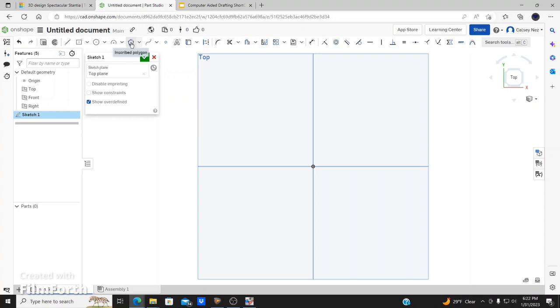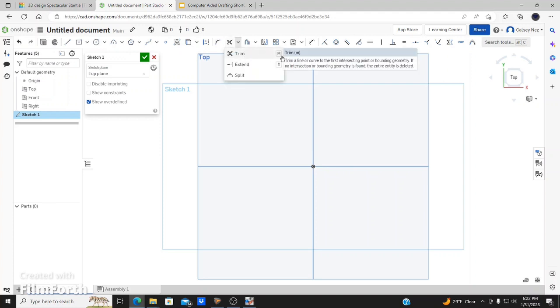Polygons, nothing else. I'll click this right here, nothing. Spline, point, nothing. Text. Then we have this project convert, which will be U. We don't know what that U is. Okay. But right now, let's cancel a command, escape. These two should have shortcuts, which are trim, M, and extend, X. Okay, so let's try this one right here.